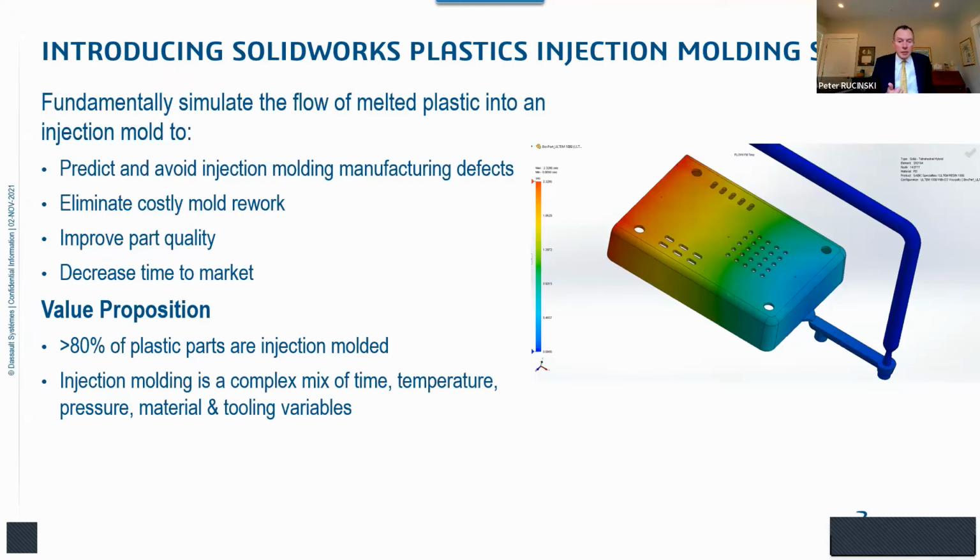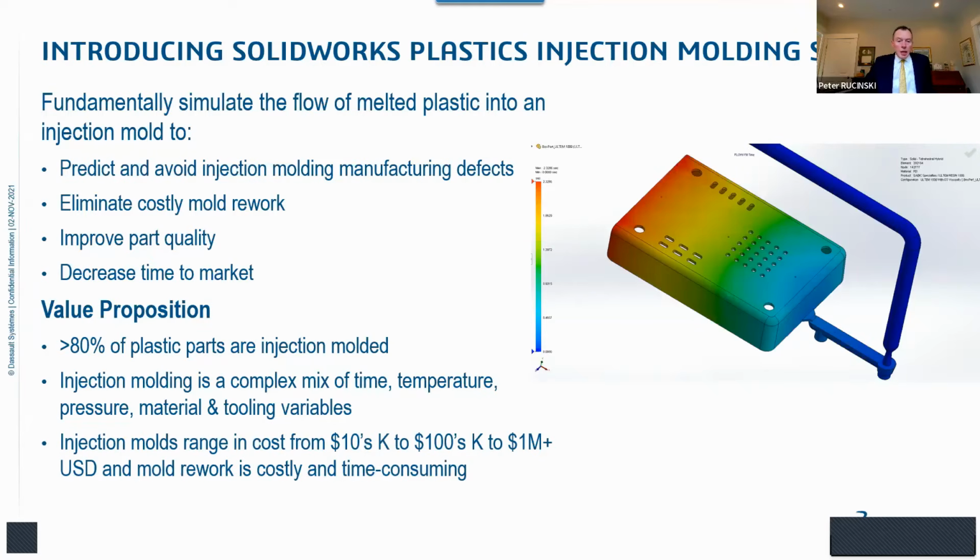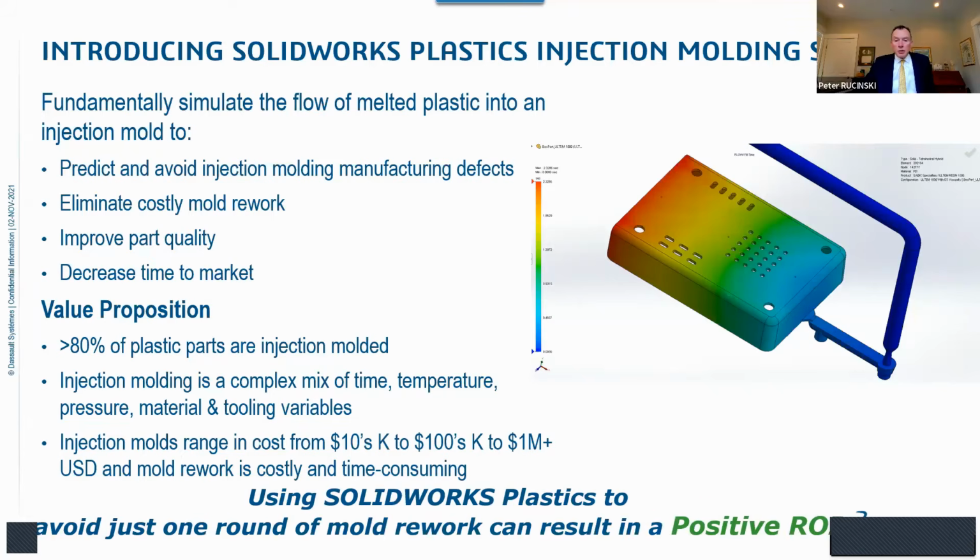Injection molding is a complex mix of time, temperature, pressure, material, design, and tooling variables. My simple takeaway there: it's very difficult to figure out inside your head how that melted plastic will flow inside the mold, especially as your part geometry gets more complex and the materials that you're using get more sophisticated. And then those injection molds can be very costly. They can range anywhere from tens of thousands to hundreds of thousands to over €1 million for just one mold. And so you could imagine that using injection molding simulation to avoid just one round of mold rework on a very expensive mold more often than not pays for one or more licenses of the software.